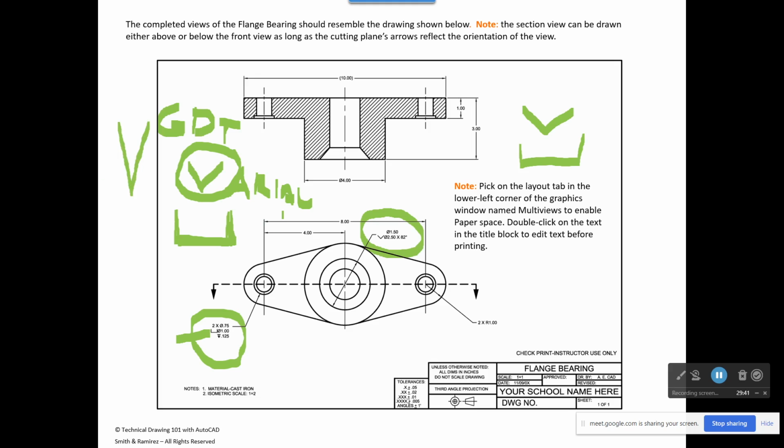You can see that on the top of page 360, and it works its way down, but it's also covered in the video. The same thing happens when you annotate a countersunk hole: you write a lowercase w. When you want this symbol here, you write a lowercase w, then highlight it and convert it to GD&T, and it changes and becomes this symbol right here.